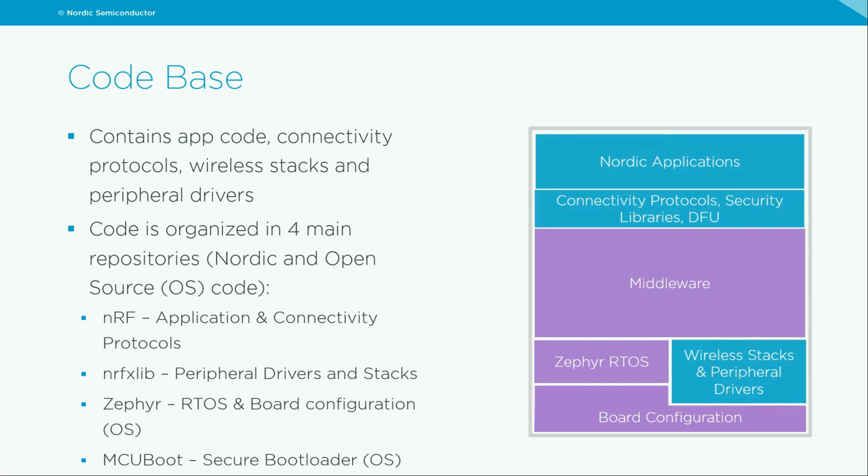Then you have nrfxlib, which has the peripheral drivers and stacks. Essentially, nrfxlib is RTOS independent libraries and modules. That can be, for example, crypto, NFC, BSDlib, etc. Then we have the Zephyr repository. And just a quick intro: a repository is essentially just a different folder. So when you have an nRF Connect SDK folder, underneath you will see these 4 different folders and a few other ones.